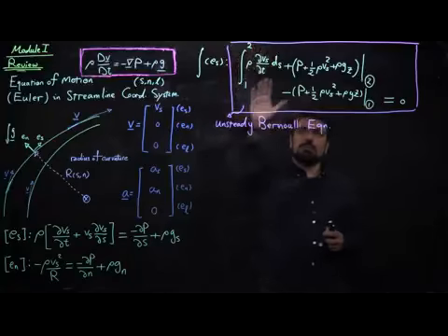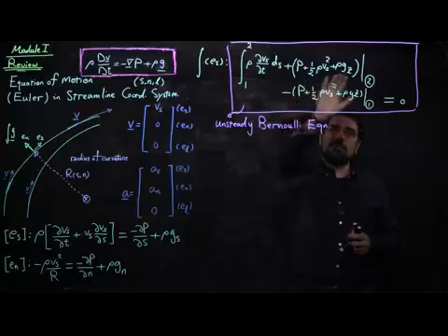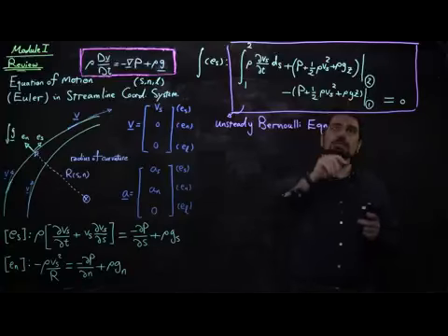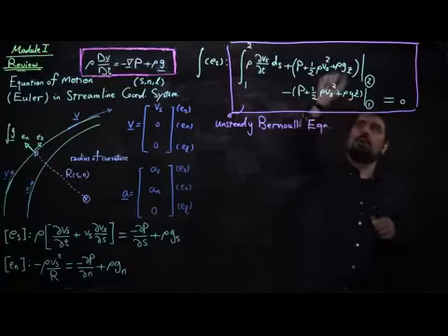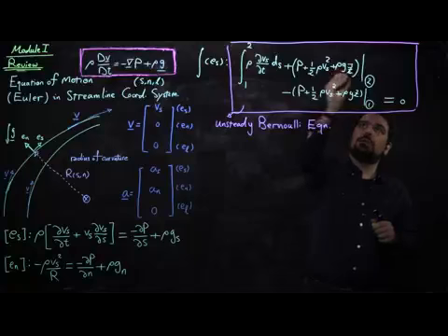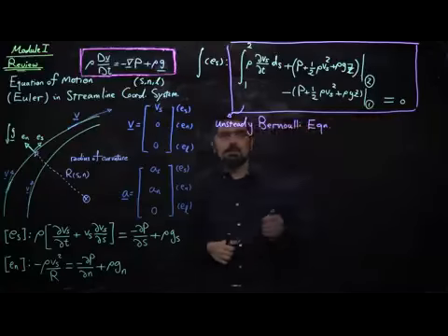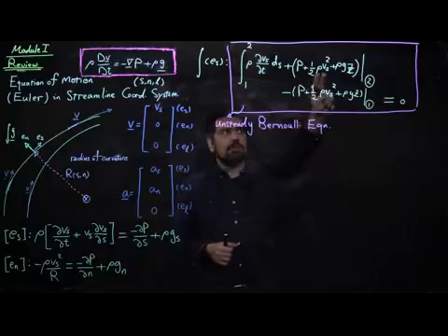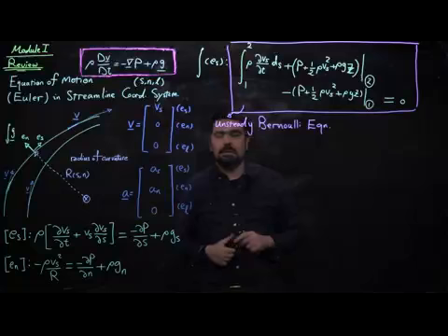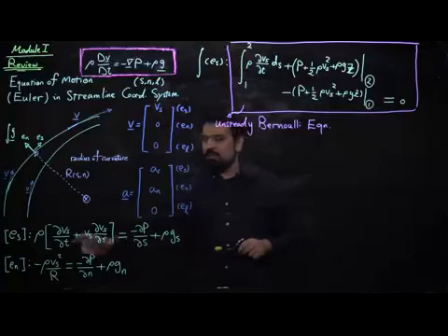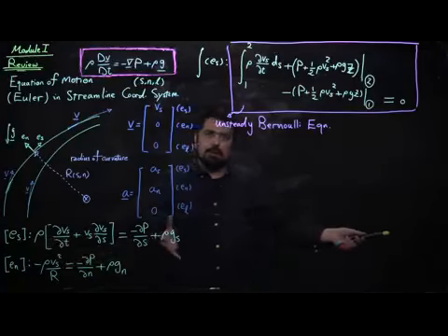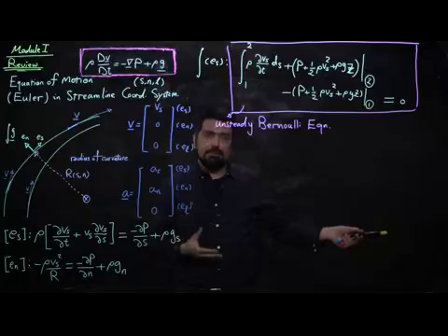And what we will have is pressure plus half rho v squared plus rho gz should remain constant as we move from one point to another point on a streamline. And this idea, as we said, comes when we integrated the force balance along the streamline.